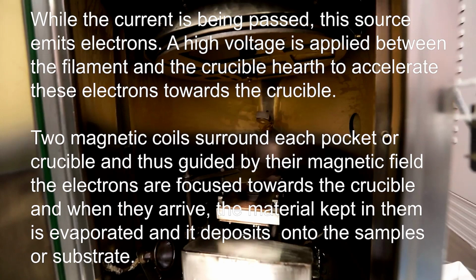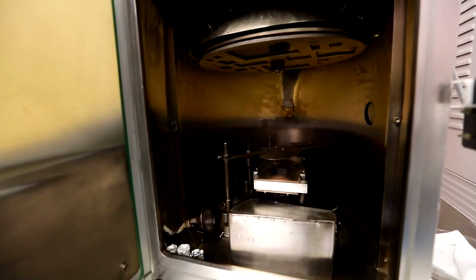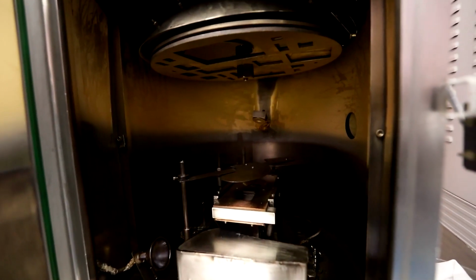Two magnetic coils surround each pocket or crucible, and thus guided by their magnetic field, the electrons are focused towards the crucible, and when they arrive, the material kept in them is evaporated and it deposits onto the samples or substrate. Now we will show the sample loading.